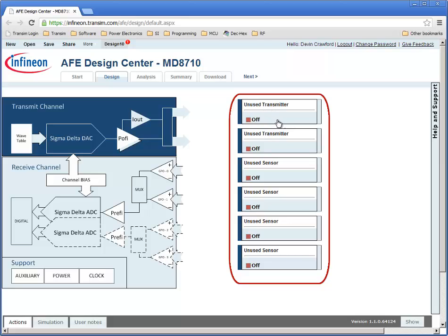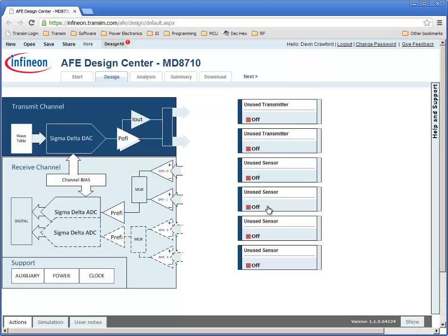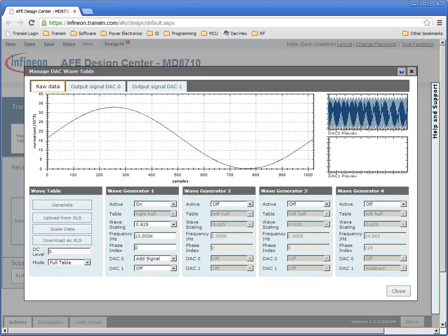The blocks on the right side of the schematic can be configured to emulate sensor functions or provide circuit-based transfer functions. The analog input, including 4 configurable op-amps, are shown on the bottom of the schematic. These op-amps provide a wide range of flexibility, including instrumentation amplifier configuration, differential voltage input, or summing functions. First, let's take a look at the wavetable.